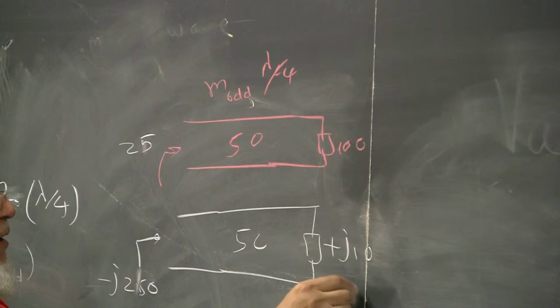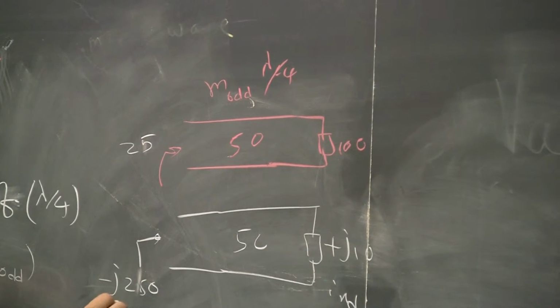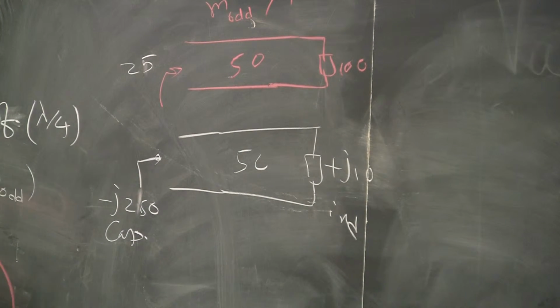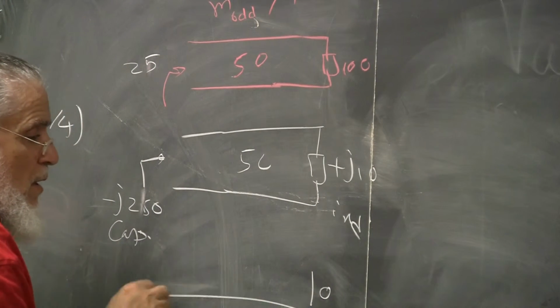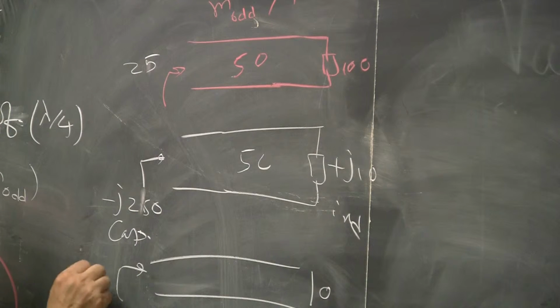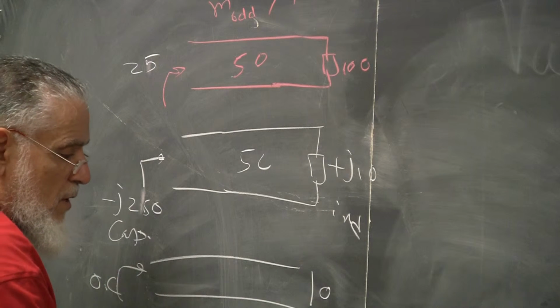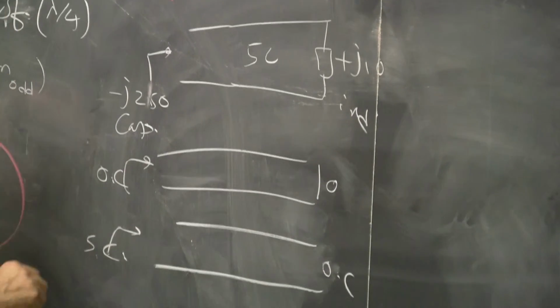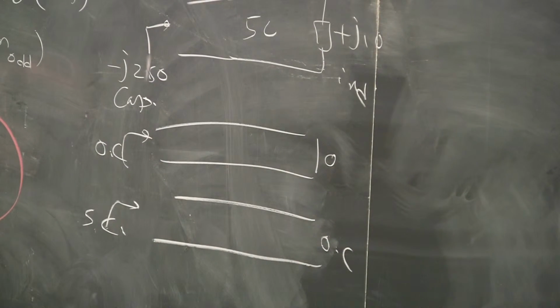So I have an inductor here, I saw a capacitor there. Well, we saw a minute ago that when we had a 0 here, we saw an open circuit, same thing. When I had an open circuit here, I see a 0 there, short circuit. It's an inverse situation.